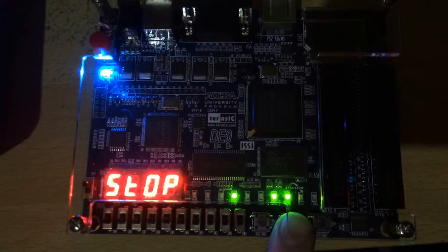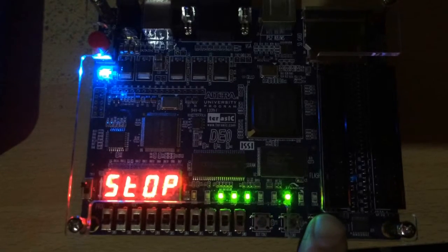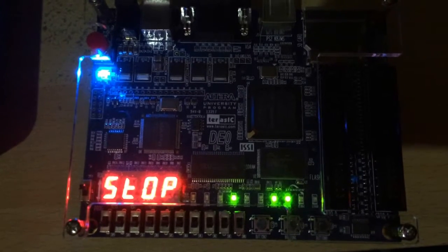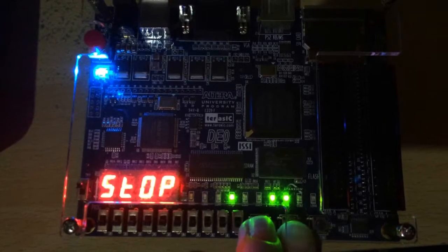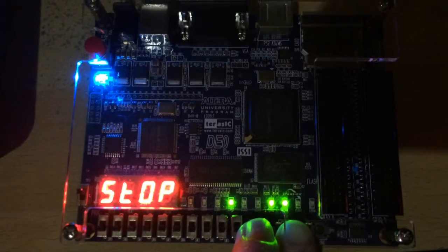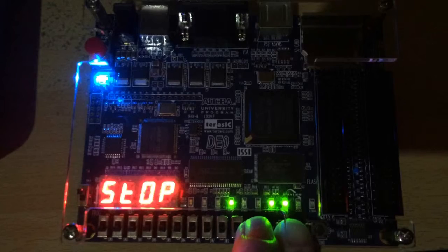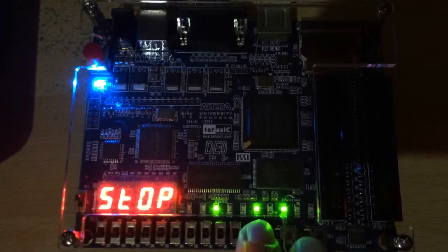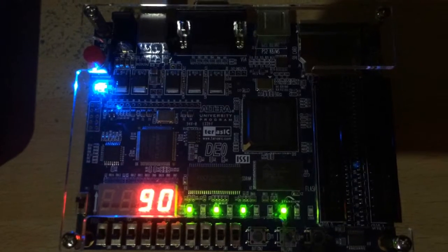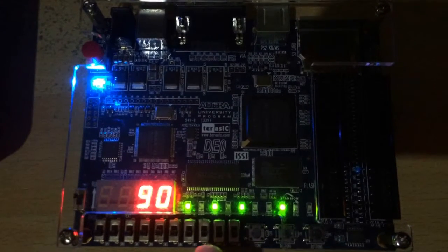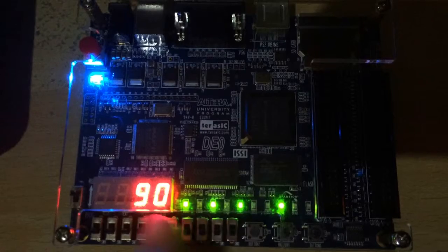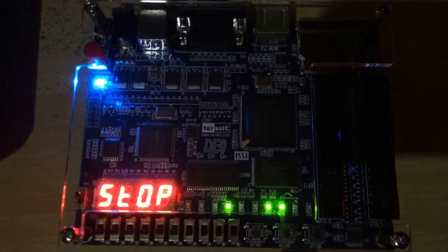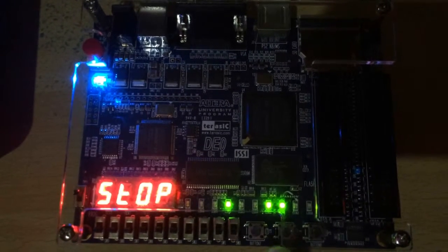I'll also just demonstrate the reset button here. So there it is, flicking through states. We hit reset, we'll come back to state A, and then I'll just demonstrate the pedestrian crossing button here. So if we hit the button for the car arriving at the minor road, we can hit pedestrian crossing in B. It's picked up in state B1, and then we go into this 5-second delay here where we're safe to cross the road, and then we'll come back to state A,